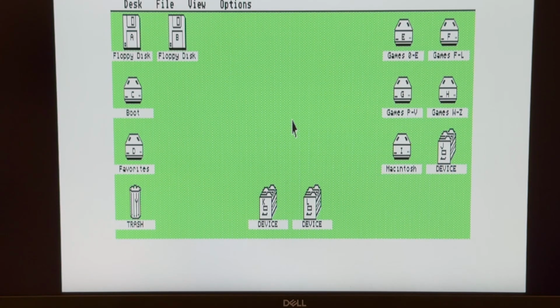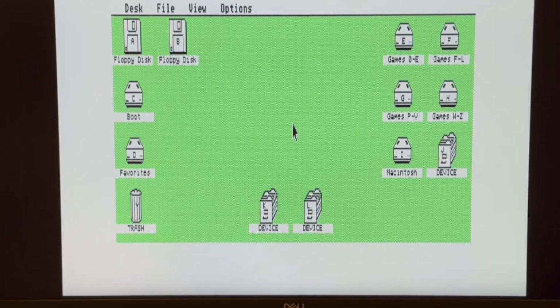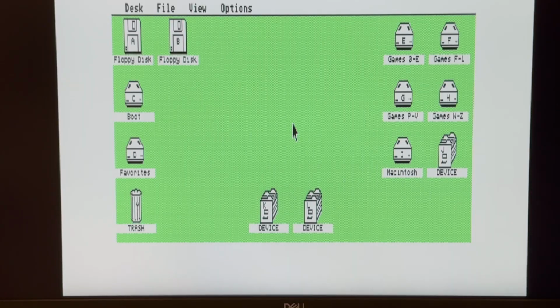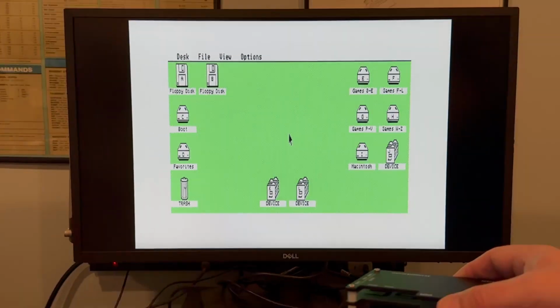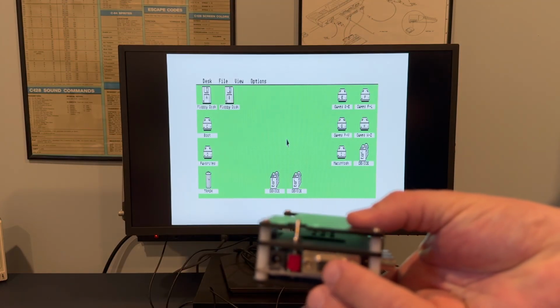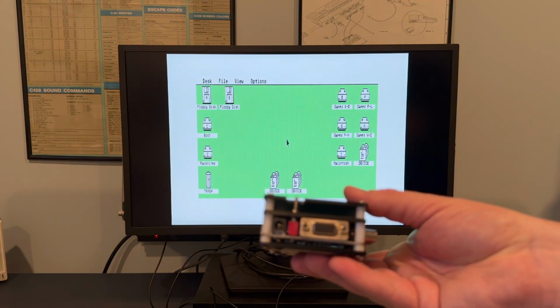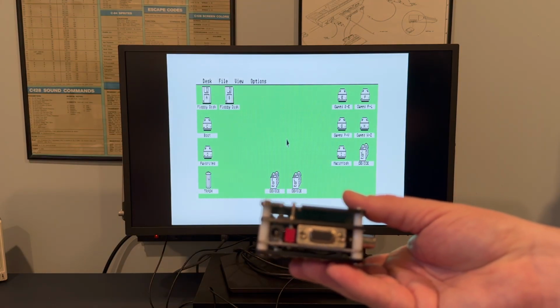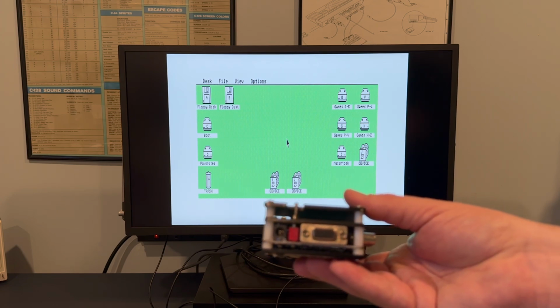Now, in addition to outputting directly to a 15 kilohertz monitor, you can also output to something like an OSSC, an upscaler. And you simply connect, let me zoom out here, to one of these OSSCs through the VGA input. Now, not all upscalers are created equal. You might find some on Amazon that are a VGA to HDMI upscaler. In most instances, they do not support the 15 kilohertz signal that an Atari ST generates.